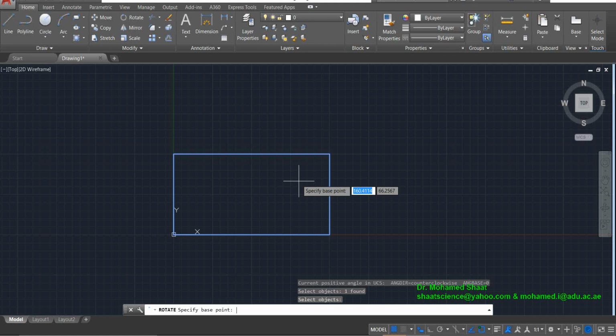and all the other points of the box should be rotating. Because to give a rotation, any object that is going to rotate should have a point that is fixed. There should be a point of rotation for any object, right? This point of rotation is the base point, as named by AutoCAD. This base point, as I mentioned before for copy or move, can be a point that belongs to the object, or any other point anywhere.